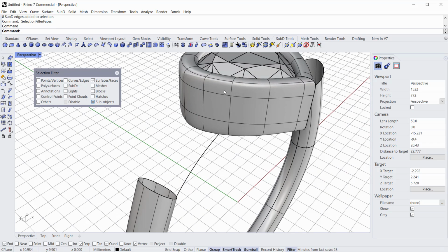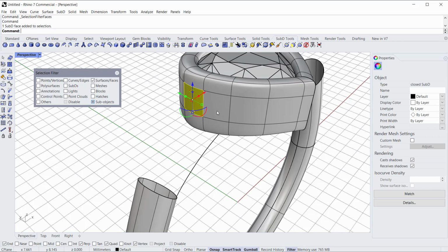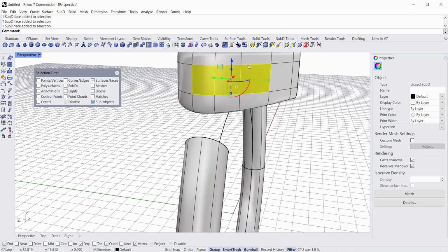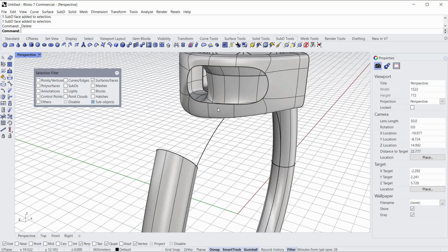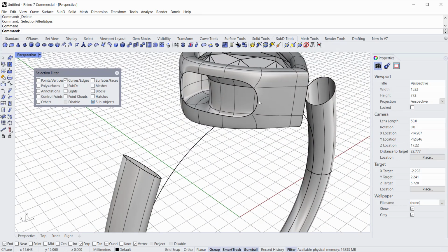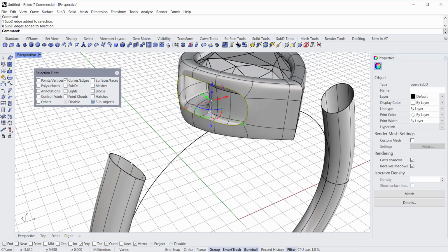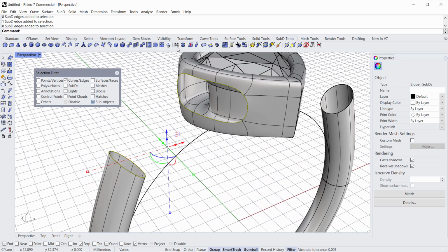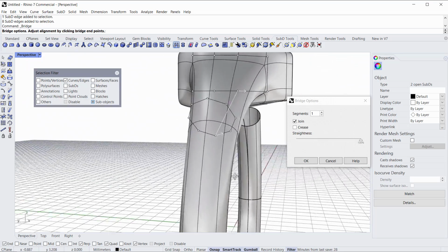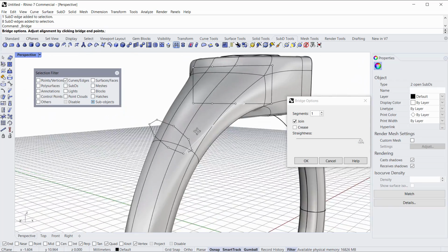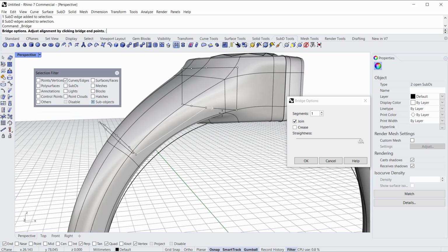Let's go faces mode here, and we'll pick you and hold shift and you and you. Okay, and so that should give us 3 across the top, 3 across the bottom, 6, 7, 8. So I'm going to press delete on the keyboard and just punch a hole right in the side of that thing. Now let's go back to edges. We'll double left click. I'm going to hold shift and double left click over here. Now let's run that bridge command. So now you can see the bridge command is like, oh, it's so great. It just made this really smooth transition between these two shapes.